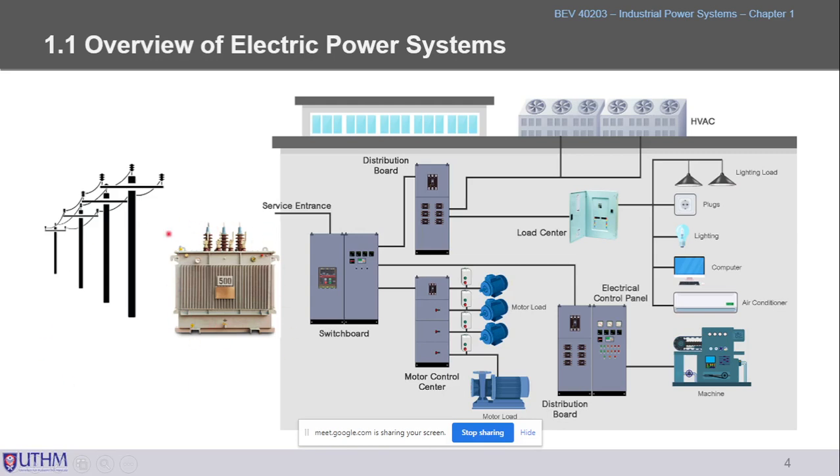And it is not only one piece of distribution transformer. They could have a few pieces of transformer. It depends on the design, that means the network layout design. So after the transformer, let's say we take from 33 kV and step down to 11 kV, for example. This is the step down transformer. So from 33 to 11 kV, and then the first thing it enters is the so-called switchgear.